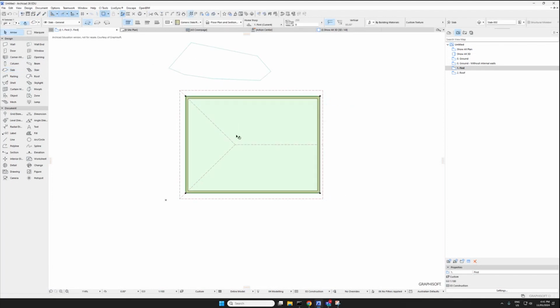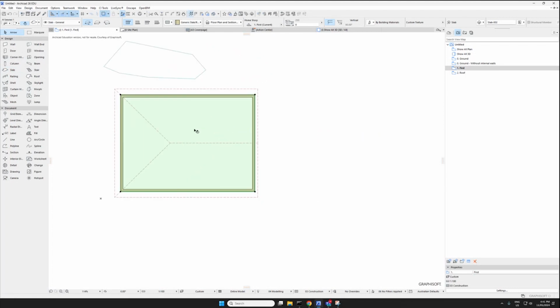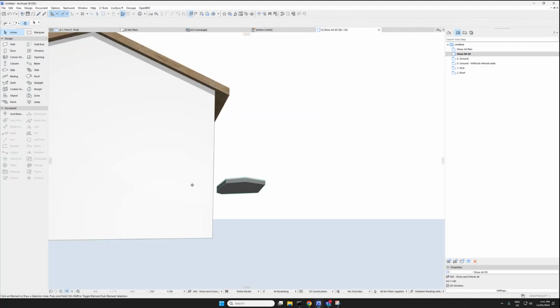So that's our slab now. If I move it across by pressing Control D, or you can actually click it and click here, Move node. You can move a node, or if you want to move the whole thing, it's drag. It's very good to get familiarized with shortcuts. It just speeds up your workflow. So Control D is to move something. Okay, now we've got a slab.